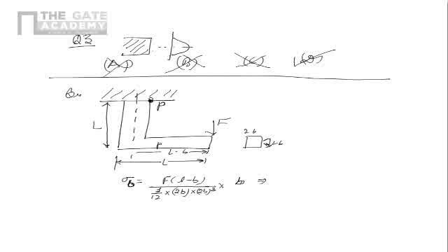So if I just resolve this, I will see it is F(L minus b) into b, upon this 12 will go up, and I have 2 into 2 into 2 into 2, so 16b to the power 4. So this will be nothing but 3 by 4 F(L minus b) upon b cube. That is the bending stress.